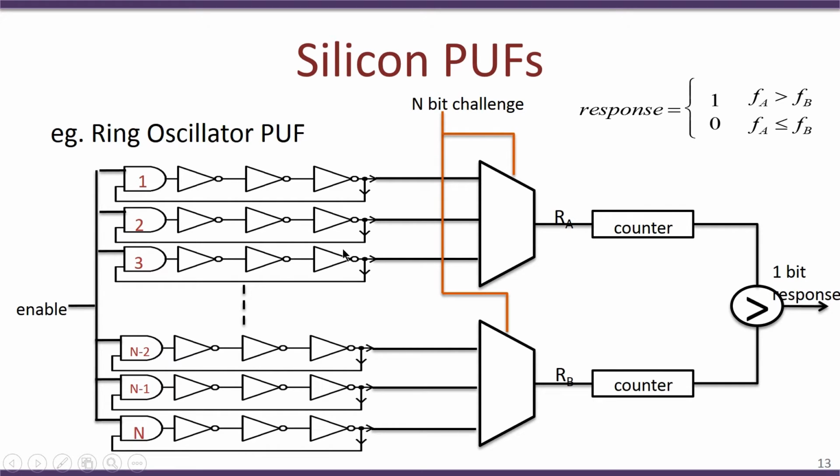If I have two exactly identical devices, each having a ring oscillator PUF, each would give me a different response for a particular challenge. One challenge gives me 1 bit of response, so if we run this ring oscillator PUF with multiple different challenges, we could build a larger output response.